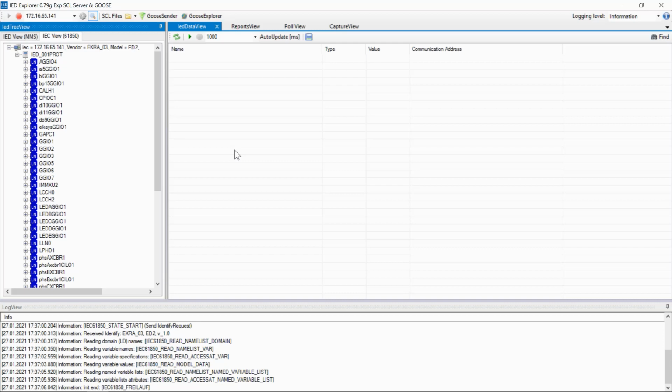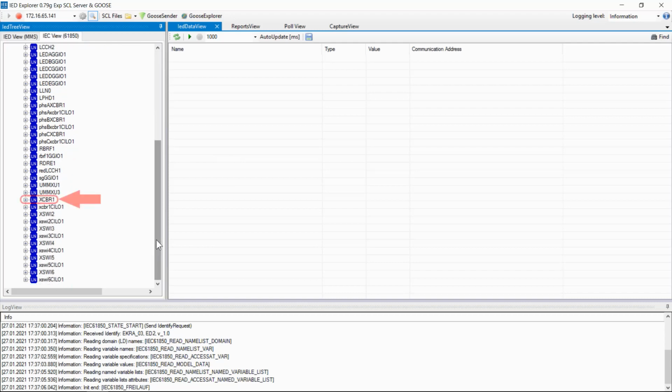In the information model of the device for the telecontrol of switching devices, certain logical nodes are used. The type of switching device, circuit breaker, corresponds to XCBR logical node, disconnector and earthing switch correspond to XSWI. The GAPC logical node is used to control equipment of various technological systems, such as ventilation systems and the like. As an example, let us consider switching a circuit breaker with a logical node XCBR1.